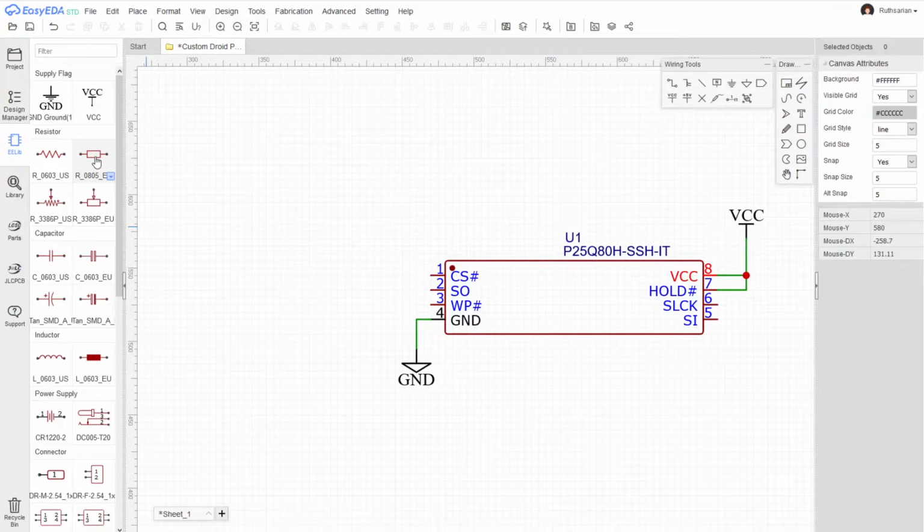It's a good balance between being a small component but still being large enough that you can solder it with your hands. When you get to really tiny components, soldering by hand is possible but not practical. So 0805 is what I'm going to go with here.